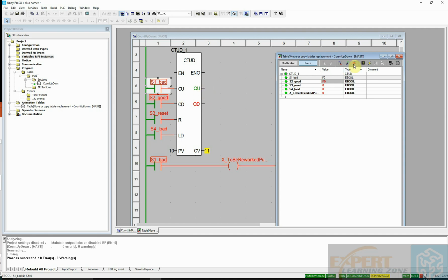All right, good. So if I now take the reset button, it should set the current counter value to 0. So this is a reset. I will set it to high. So the current counter value goes back to 0. This is what we're saying, that our counter will reset when I press this. And if I go to the load terminal and I load it, then this value 10 should go to the output like that.